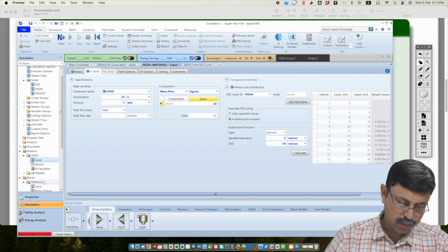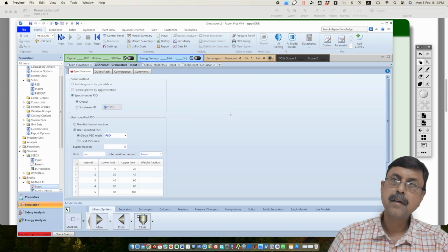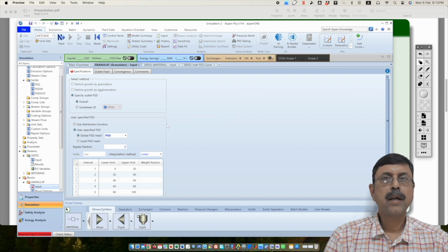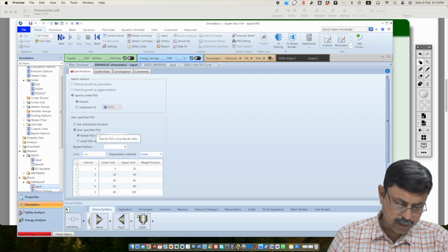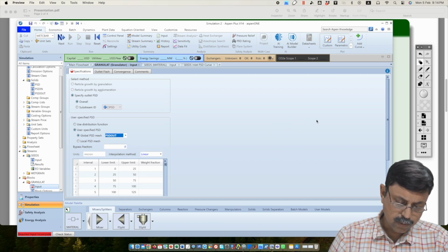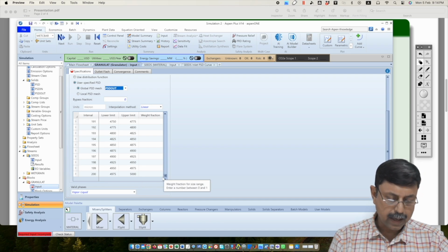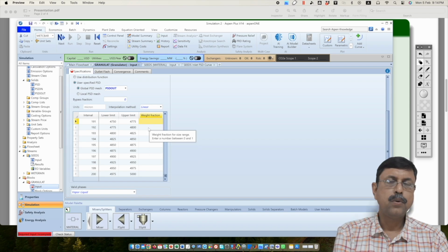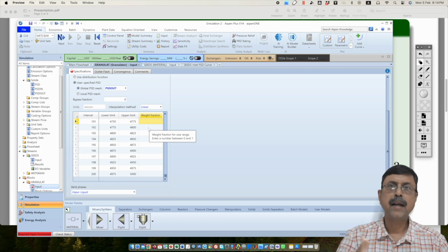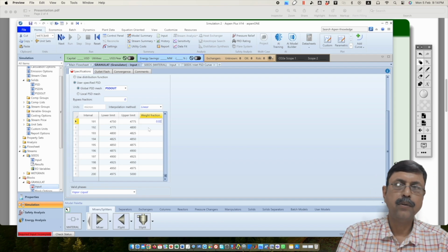Okay. Now you go to the granulator input. Here you see the outlet particle size distribution option is only open for you because you do not have any binder or hot air, and you have to choose the outlet particle size distribution, which is PSD out. And here you can give the information from 0 to 5,000. The entire region, what is the outlet weight fraction that you want, that information you have to put in. Suppose you want 0.02 weight fraction of entire granules to fall between 4750 to 4775 micron, then you just put in the value of 0.02 over here.